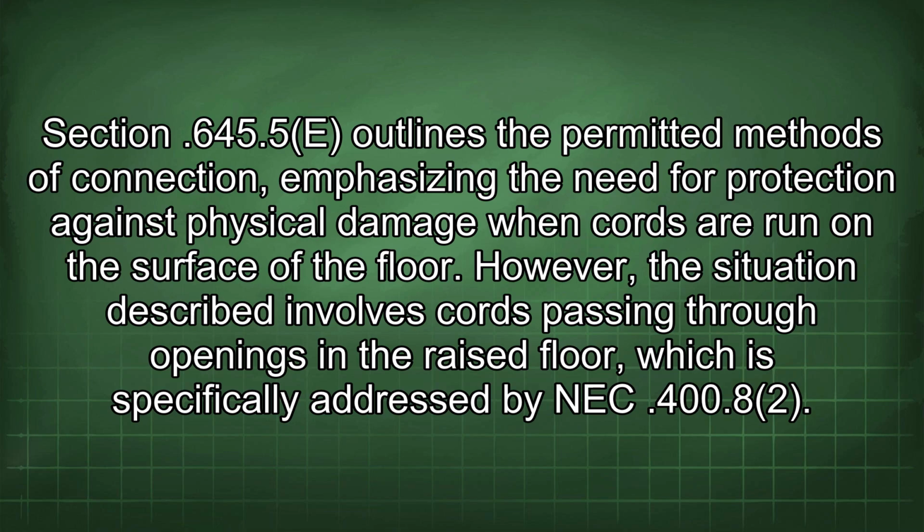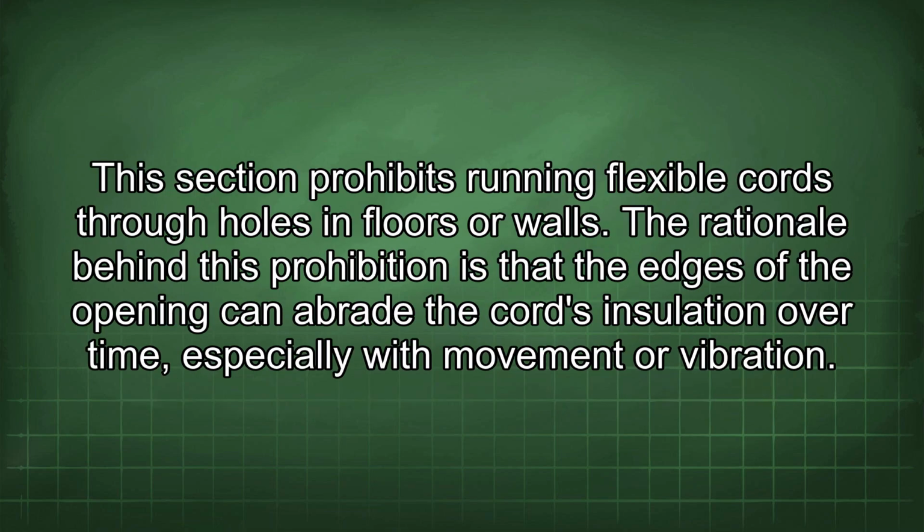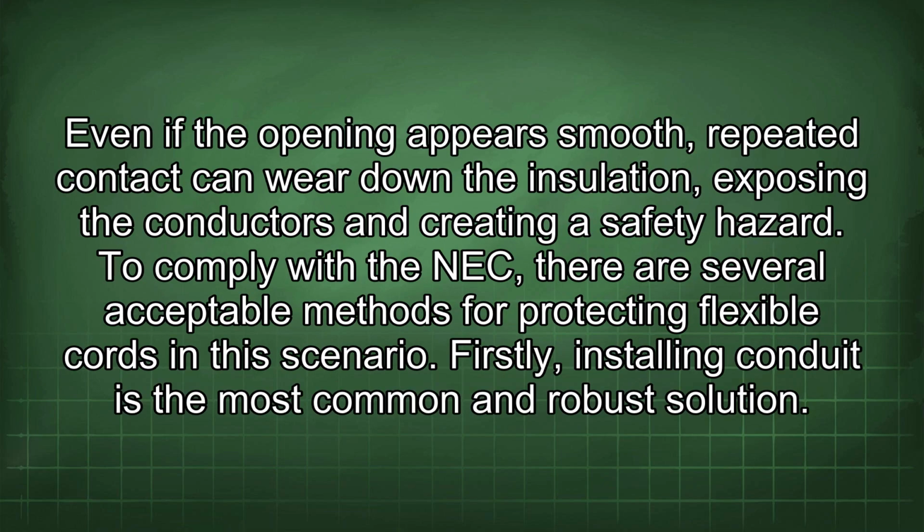However, the situation described involves cords passing through openings in the raised floor, which is specifically addressed by NEC 400.8. This section prohibits running flexible cords through holes in floors or walls. The rationale behind this prohibition is that the edges of the opening can abrade the cord's insulation over time, especially with movement or vibration. Even if the opening appears smooth, repeated contact can wear down the insulation, exposing the conductors and creating a safety hazard.